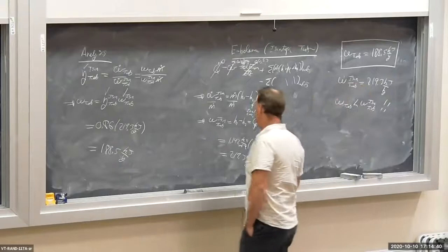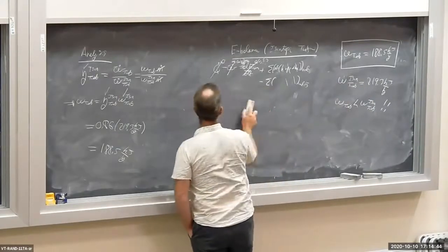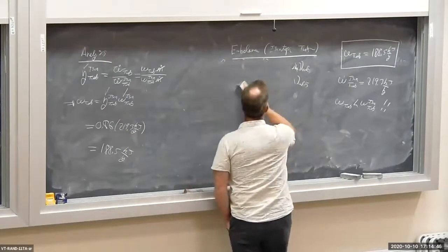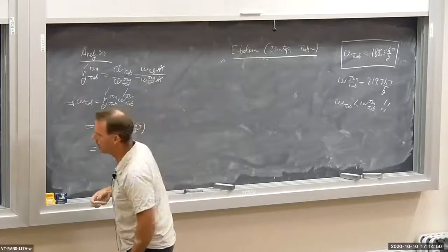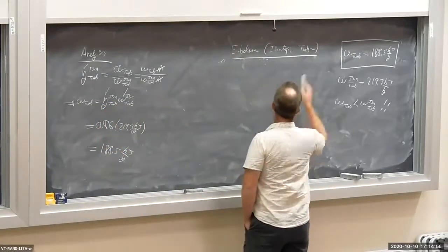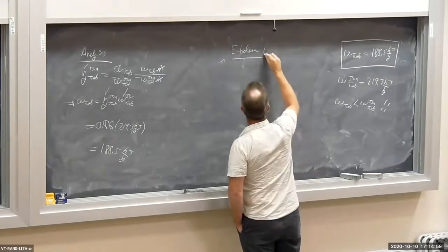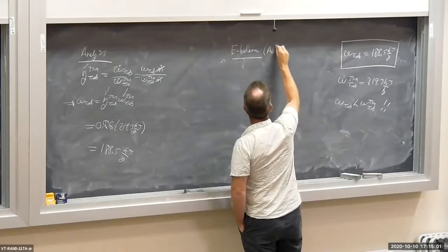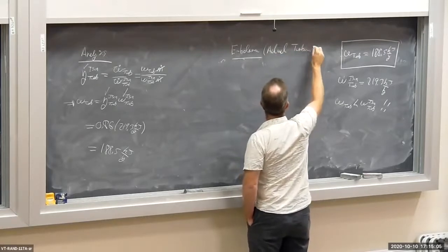Let's calculate the actual outlet temperature. The actual outlet temperature for the real turbine, T2. We've already calculated T2 sub S. What was that? 1,008 degrees. Let's calculate T2. Let's apply the energy balance to the real turbine, the actual turbine.